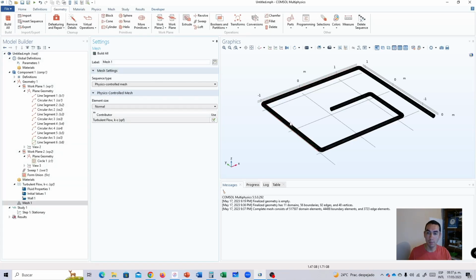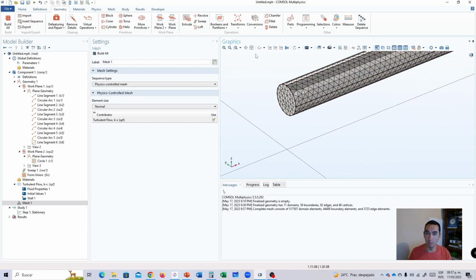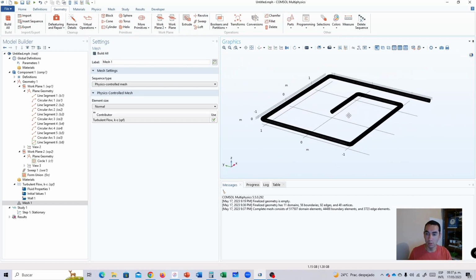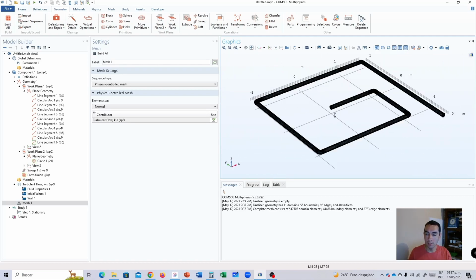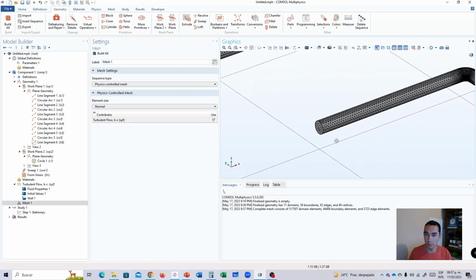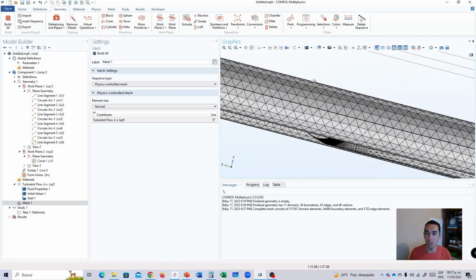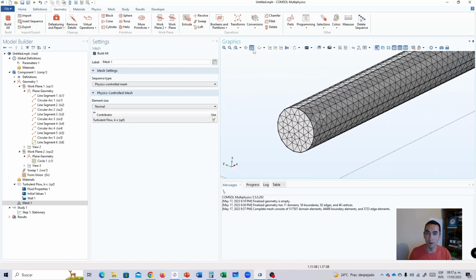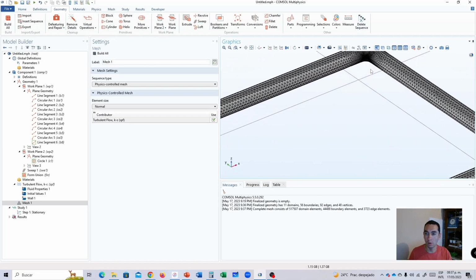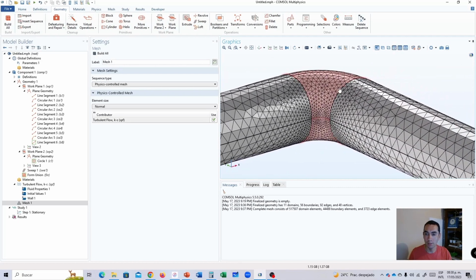The generation of the mesh can take a little bit long, but it's going to depend on your computer and your computational resources. Here I think that is enough with this for this example, but you may be willing to change in order to refine or make it coarser according to your computer or your demands.